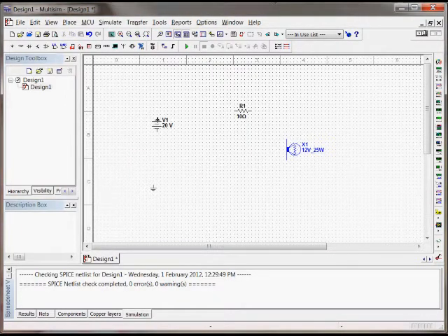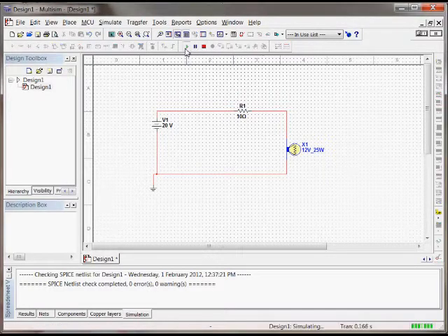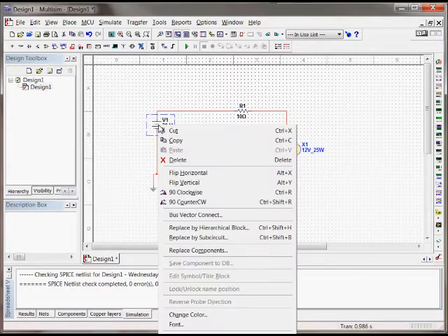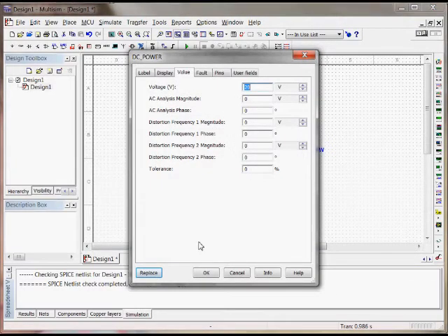Multisim is a modeless wiring environment, therefore Multisim will automatically know when you are trying to wire up your circuit. If we turn on the circuit, it will start simulating and you will see the light globe turn on. If we change the value of the power supply to high and simulate, the element in the globe will blow up, as it would in the real world.